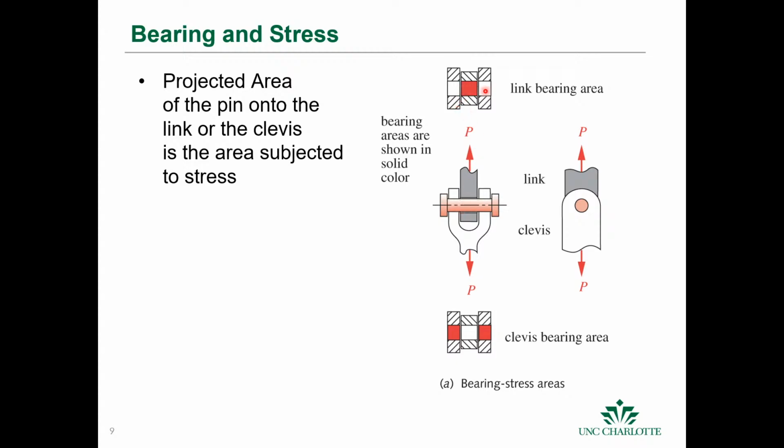And so the bearing stress is going to show up here in the link. It'll also show up in the clevis. Okay, and this is not just for this. This is just an example of where we have a pin or bolted joint. And so the bearing stress is going to show up here on this area of the link, and also on these areas under here of the clevis.